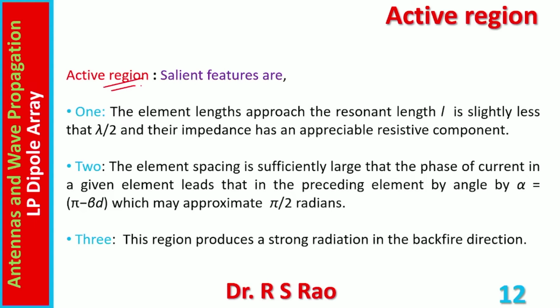Now active region, its salient features are: 1. The element lengths approach the resonant length L, but is slightly less than lambda by 2, and their impedance has an appreciable resistive component.